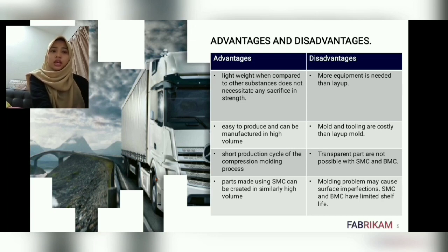For the disadvantages of this process: first, more equipment is needed than layup. Second, mold and tooling are costlier than layup molds. Third, transparent parts are not possible with SMC and BMC processes. Fourth, molding epoxy has limited shelf life.